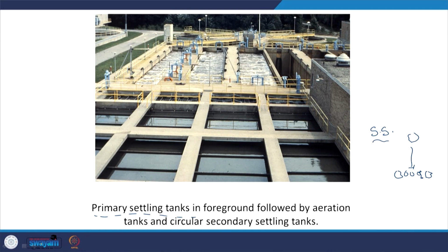But did they design it as a CSTR? Not really. So, how did they design it? They designed it as if the flow was going in this direction and again this direction, like a semi plug flow, or they were trying to achieve plug flow reactor conditions, right. So, that is what you see, it is neither a CSTR nor certainly a completely plug flow reactor, but they were trying to achieve plug flow reactor like conditions.